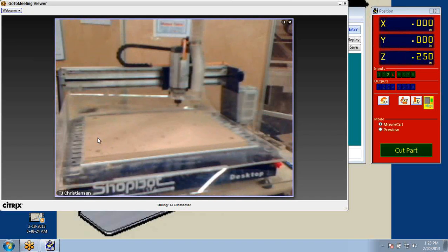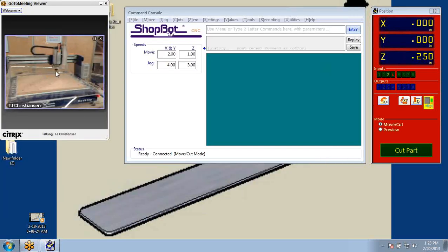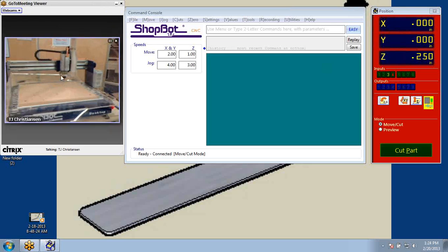These are switches that are built in, so when we do a homing routine, the machine knows how far it can go over, stops, records that measurement, comes back, tests it once more, double checks the measurement, keeps that measurement remembered, and then goes and checks the next one. That's how it knows to always go back to the same 0,0 location. Because right now it says that 0,0 is way out there. I know that's wrong. So how do I get the machine back to the proper 0,0?